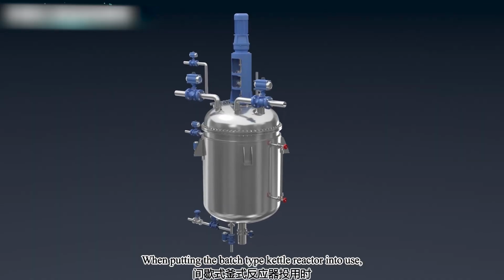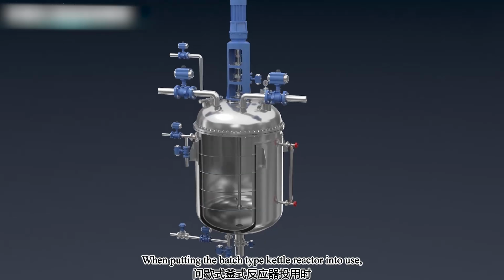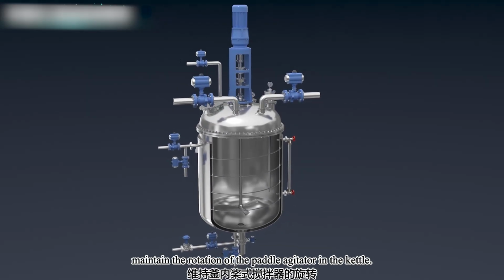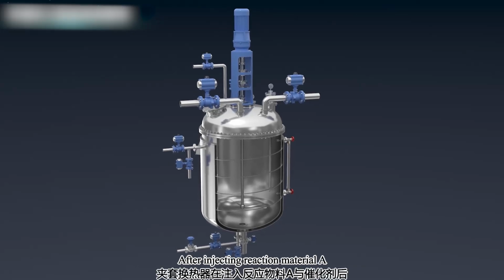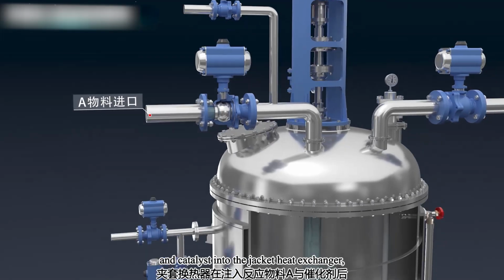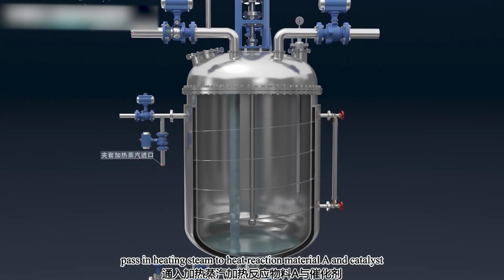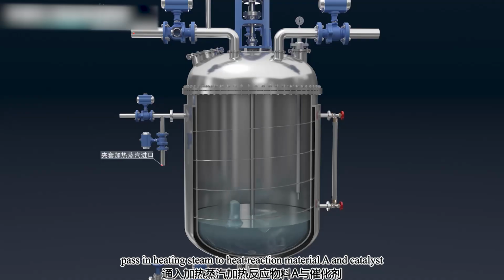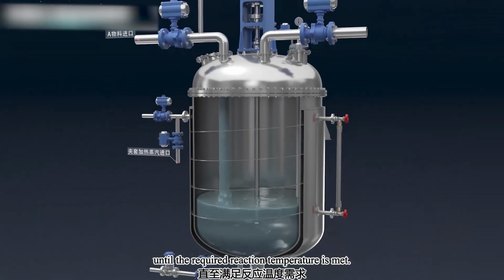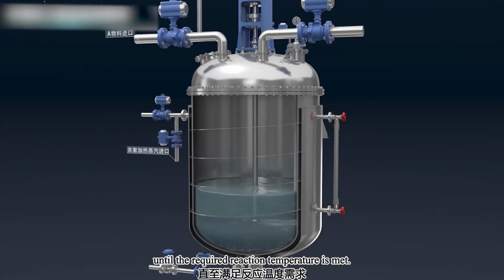When putting the batch-type kettle reactor into use, maintain the rotation of the paddle agitator in the kettle. After injecting reaction material and catalyst into the jacket heat exchanger, pass in heating steam to heat reaction material A and catalyst until the required reaction temperature is met.